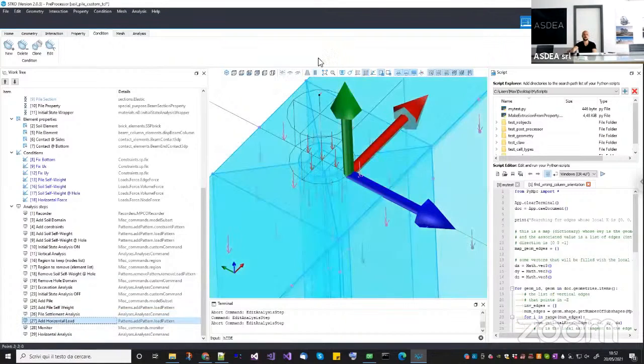So I just need to add, we have a question. Vance, is it possible to add the pile before removing the elements to simulate a wall-stabilized excavation for the pile? I tried this on my own, but it crashed, probably only due to the load you mentioned. Yeah, probably it crashed only for the same reason. Of course, you can. You can put the pile here because actually the pile is connected to the nodes on the boundaries, and those nodes are still there. So even before and after excavation. So if you want, you can do it. There is not a problem.